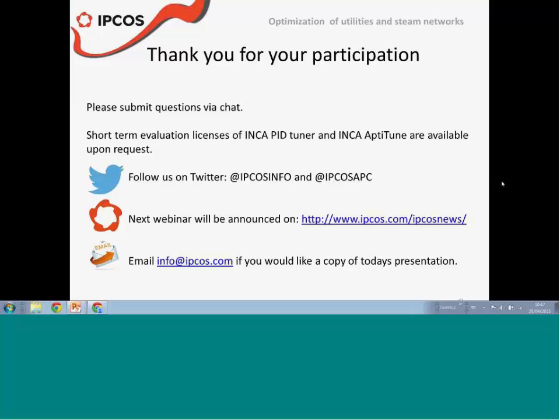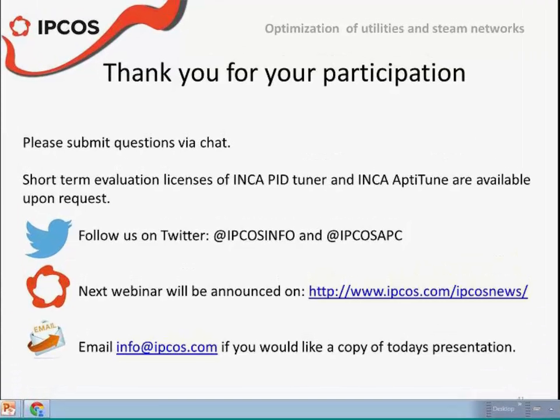Well, the IGVs in that case can be fixed, because the IGVs have much more effect on the duty of the controller than on the pressure. We saw that the IGVs were left at the same position for weeks and weeks, with no major changes in the feed to the column, and the pressure controller was still working. So in that case, yes, the IGVs can be fixed. That's not a problem.